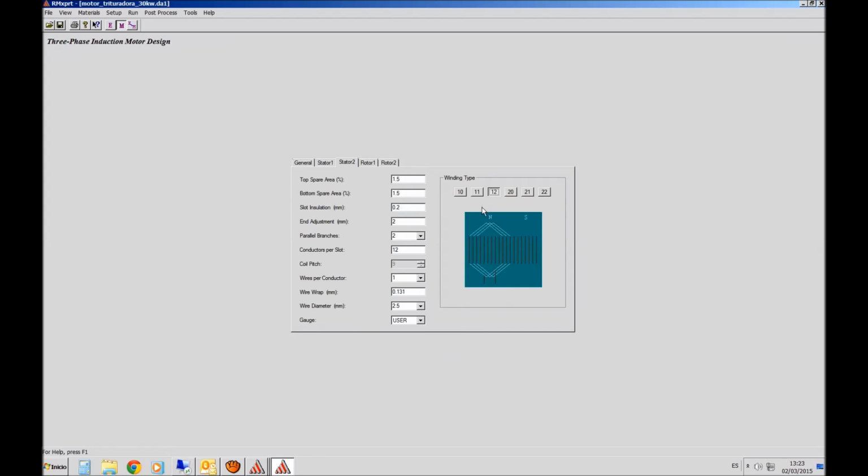As you can see, we've got different type of winding too. You can have two possibilities for your own design of the winding. In number 10, you've got the possibility of designing single layer windings, and in number 20, you can design double layer windings. Of course, to do it you only have to follow the rules I gave you during the classes.